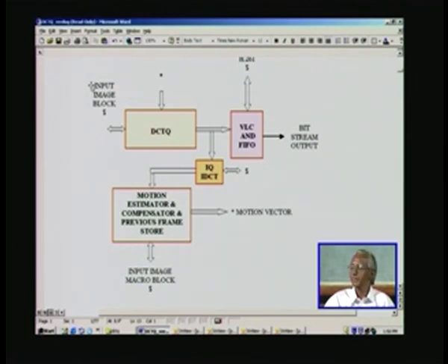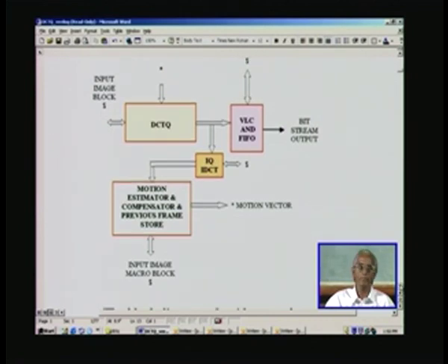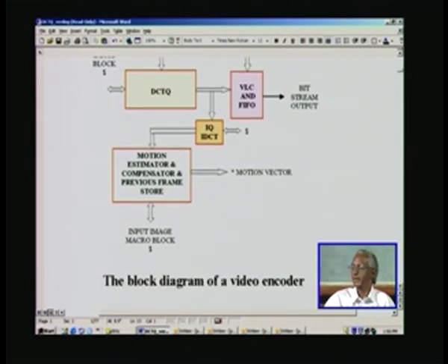Ideally we will be having a look at the images that we get out of running our design using both MATLAB as well as Verilog later on. So is this clear to you? This is the encoder, its counterpart is the decoder. So what goes out is a highly compressed stream. For example, whatever the image, you compress by a factor of 10 to 50 anywhere, and then only send it. Thereby you reduce the bandwidth requirements as well as storage at the receiving end.